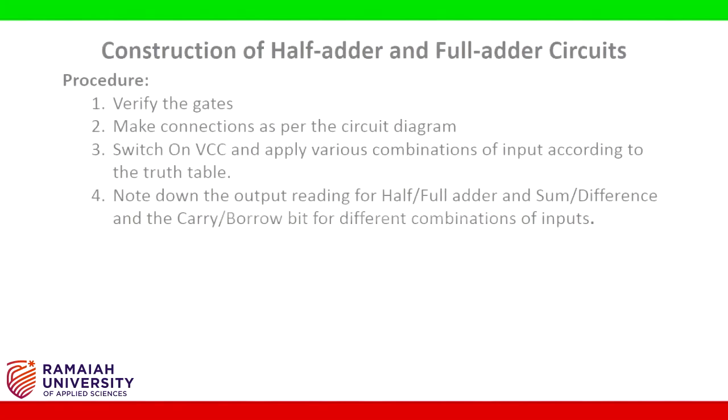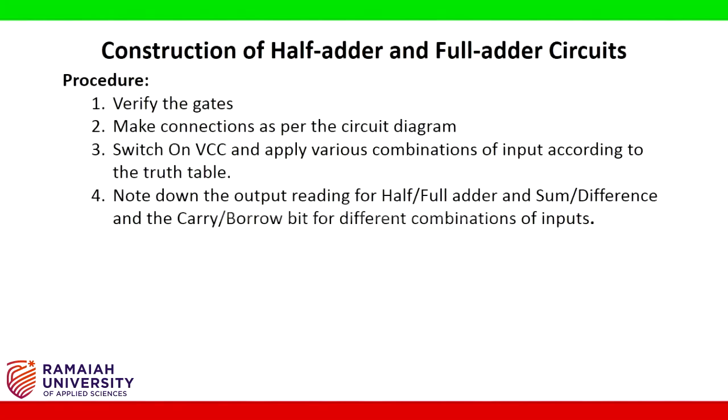Procedure for verification of adders. Verify the gates. Make connections as per the circuit diagram. Switch on VCC and apply various combinations of input according to the truth table. Note down the output reading for half adder, full adder, sum, difference and the carry, borrow bit for different combinations of inputs.